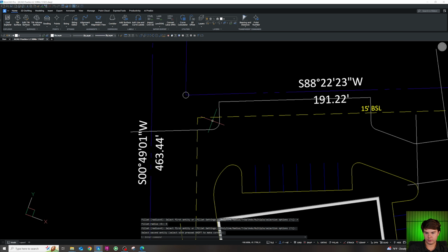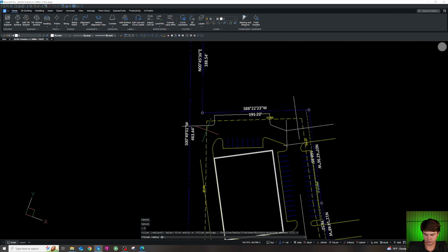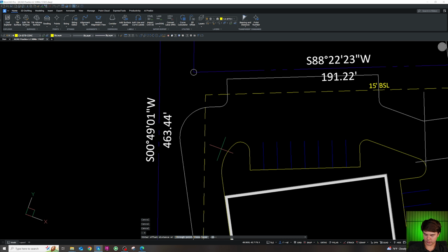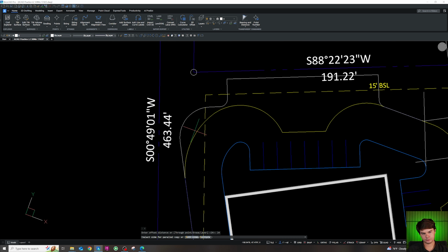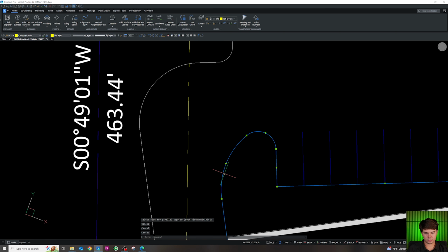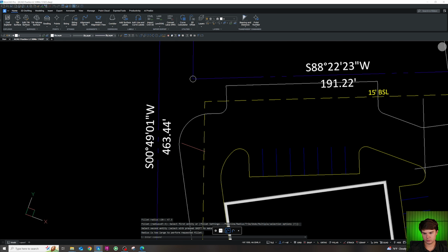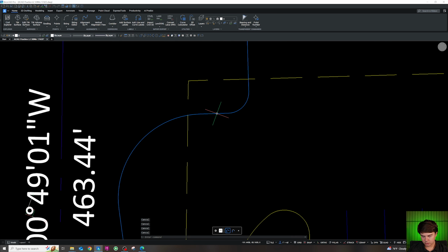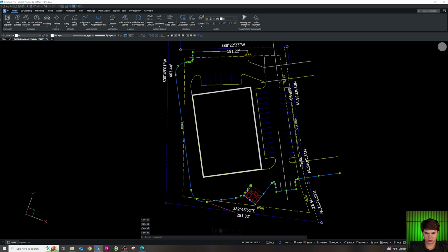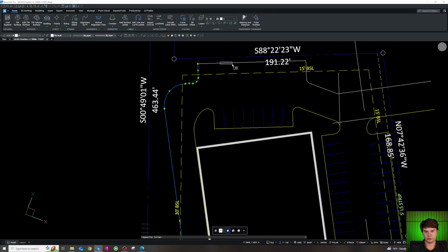Okay, so we've got our curve through here up to our parking, which is going to connect to right here. And then it looks like this has 20-foot radius. Although typically I like to offset this 24. This is a 23-foot radius, so I like to add 24 feet to that. Give this a 47.3 radius, or we'll just leave it at 20. So now that our curb wraps all the way around, we'll join this all up.